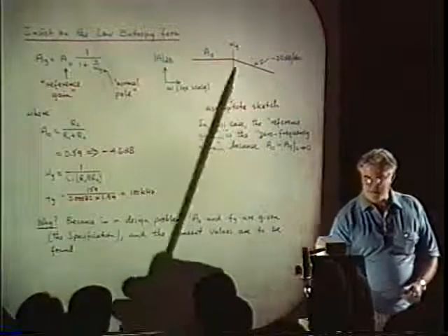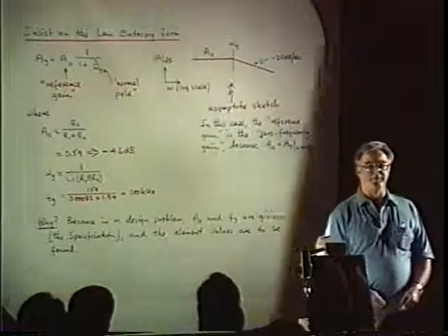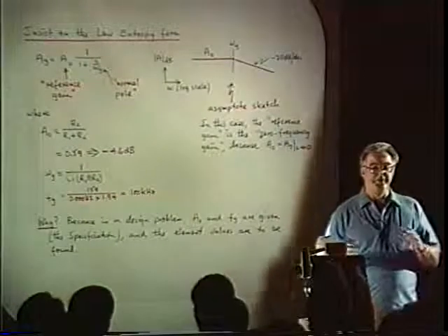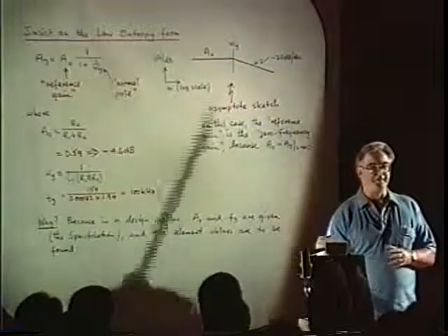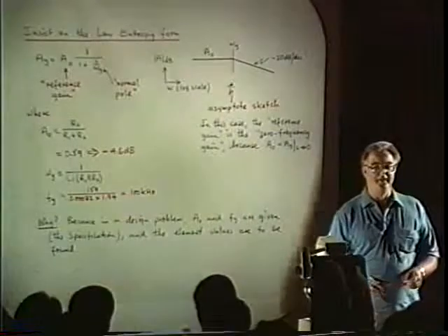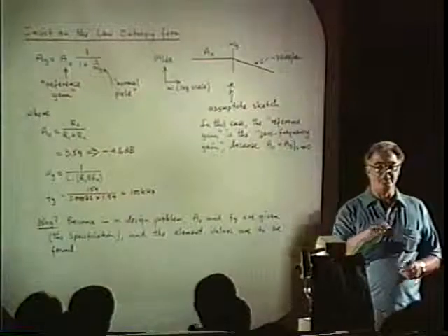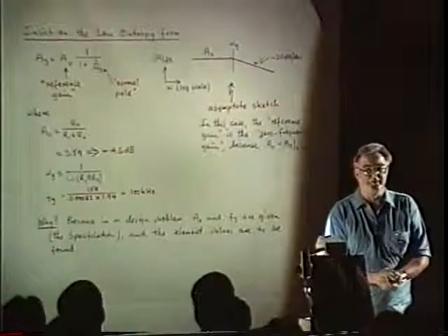Of course, the actual magnitude function has a smooth 3 dB down corner at that point. But the geometry of that corner is fixed. It's always the same. Whenever you have an asymptote intersection like that, there is always that same geometry smooth curve that goes through that point. So you don't have to draw it all the time.